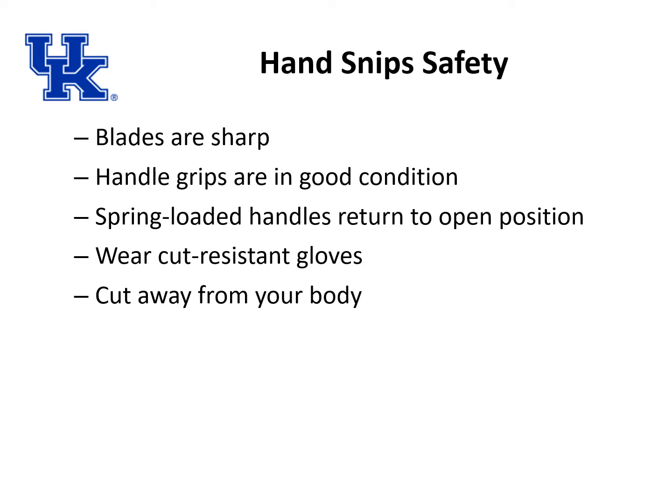When using hand snips, blades should be sharp. Handle grip should be in good condition to prevent slippage. Spring-loaded handles should return to the open position. Wear cut-resistant gloves if cutting sheet metal, and cut away from your body.